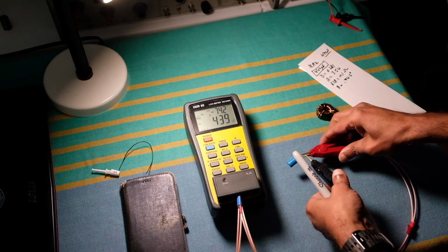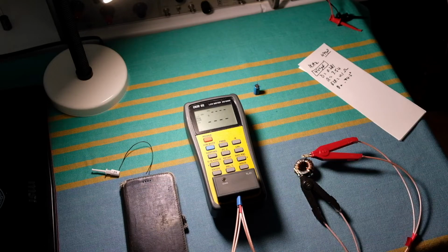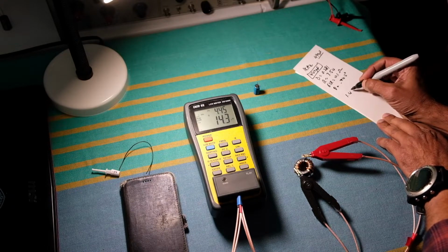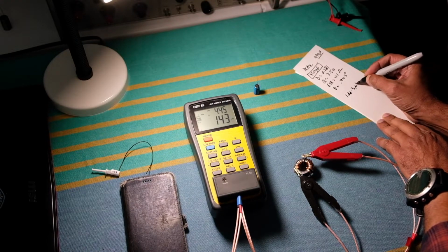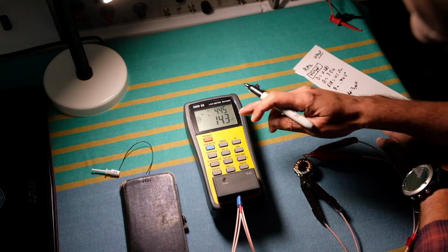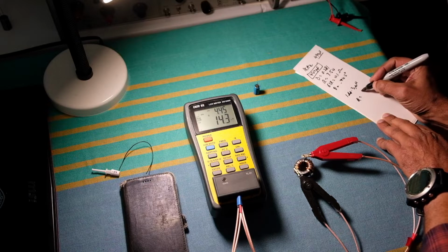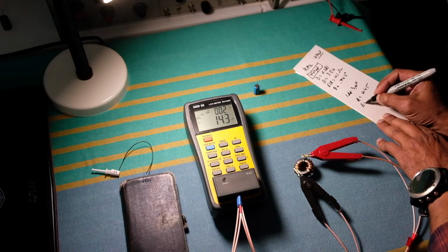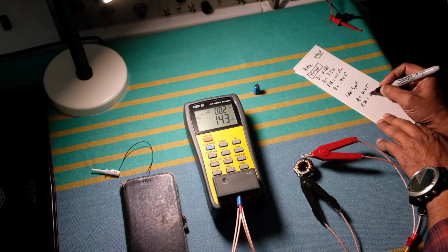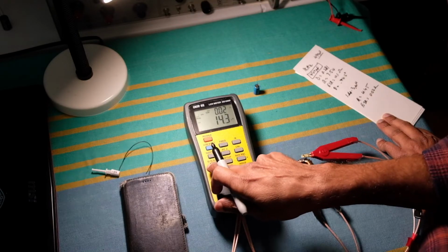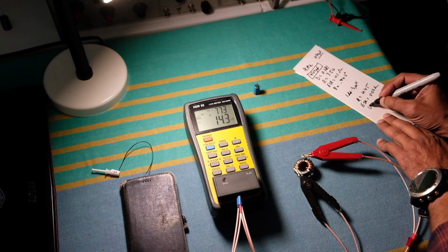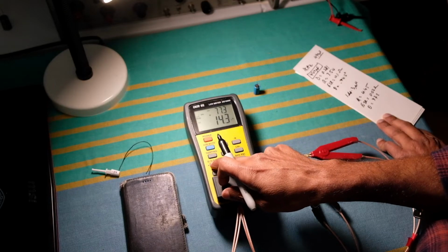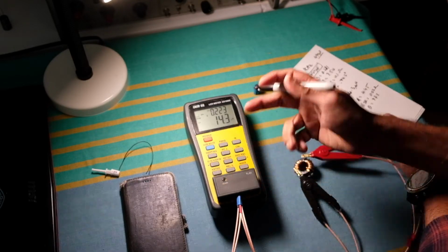Now we'll do the measurement of the inductor. So the inductance at the same frequency, 1 kilohertz, is 14.3 microhenry. The Q is 4.45. ESR is 0.02 ohms. Theta, now this is a positive number which we expect, 77.3 degrees, and the D is 0.223.